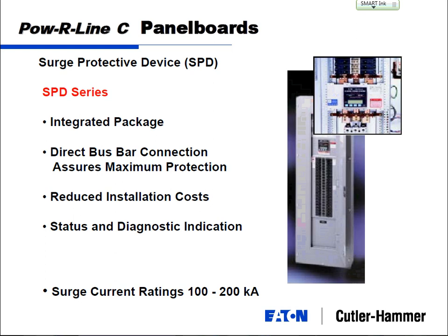Now, what does this do on this panel board? Well, if this is a main switchboard or something, and you have any lightning coming in, it's going to shunt as much as it can to ground at the panel board, so your loads coming out of your branch breakers aren't going to see that. Similarly, the internally generated transients that are coming from your copier machine or any other equipment, once they go through that branch breaker and hit the panel board bus, this again will shunt the high voltages to ground.